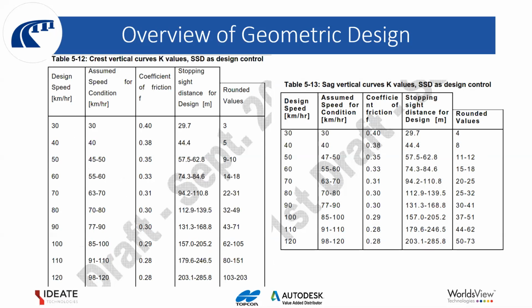So this is what I'm saying: if you are approaching a particular curve within a vertical alignment, the design speed will directly be determined by the grade that you are achieving on that particular slope, and correspondingly by the sight distances, that's both passing and stopping.